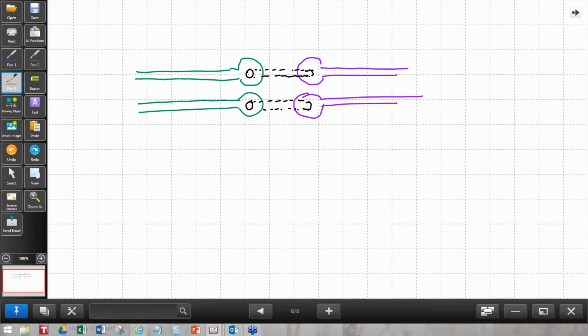So I'm just trying to schematic diagram this out. If this is the diff pair, and the other side is the continuation of the diff pair, and you have some kind of vias going between them, you need to make sure those barrels stay clean, okay?